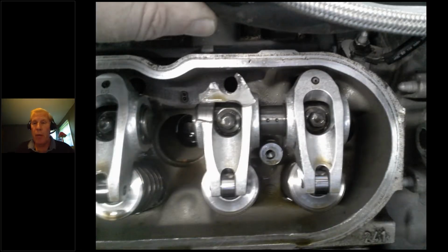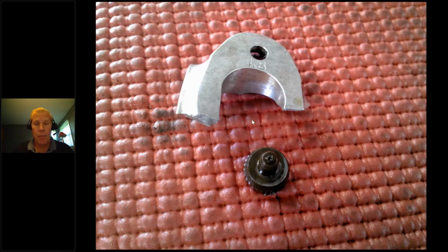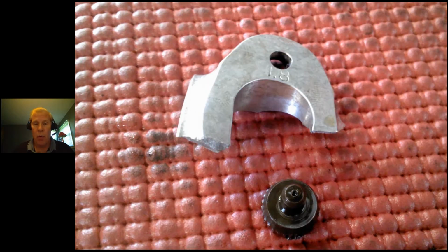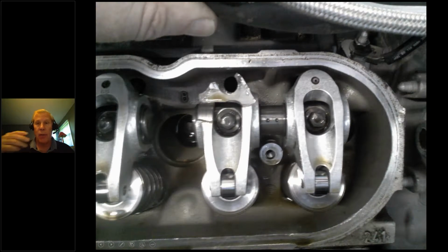So we did some preliminary investigative surgery, if you will, pull the cover. And obviously you can see by looking at the high performance rocker, the tip of it is broken. Now the push rod was there, I removed the push rod. And fortunately, we found the parts. So that worked out pretty well. You can see how clean the engine is. So I'm guessing under a high boost condition, it busted it. But I don't really care about that. The bottom line is that we have an intake valve that's not opening.